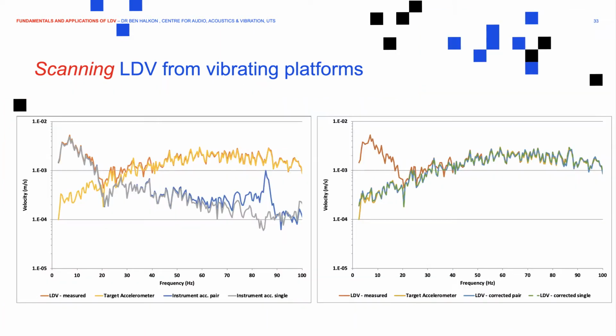There are some issues around some frequencies where we don't get such a good improvement, and that's as a result of the fact that the 2 DC response accelerometers that we use are mounted to the front panel, which happens to be flexible itself, so the measurement that we make doesn't really give us the correct subtraction measurement that we need. So we use the single accelerometer mounted on the laser beam path instead, and we get a proper correction at that frequency.